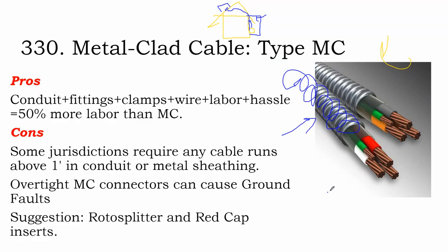So when I'm buying my MC cable, one of the things that I'm checking is, even though the MC cable has a damp rating, I want to make sure that the cables inside of it are THWN, wet rated cables, so that I can put it into EMT conduit at that point for the rest of my run down to the inverter.